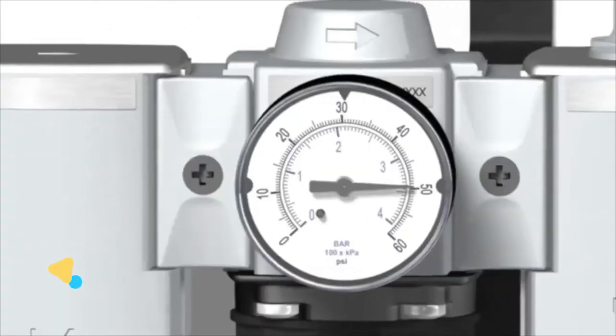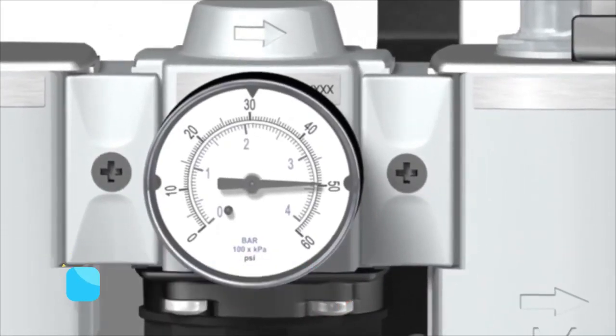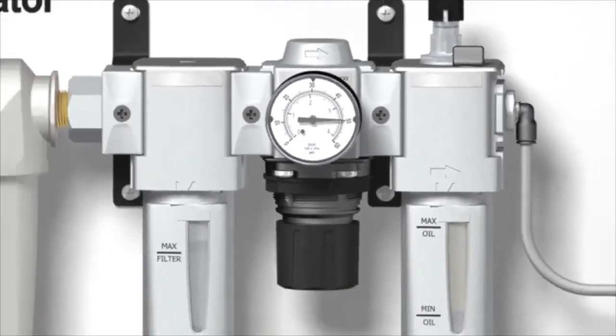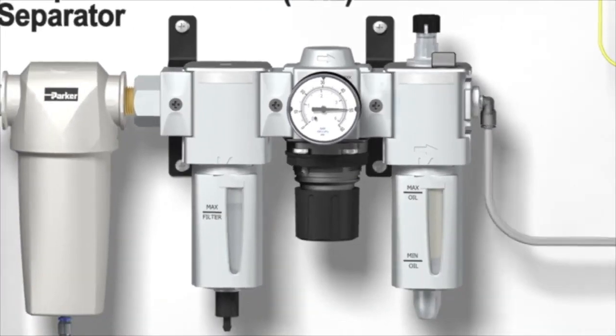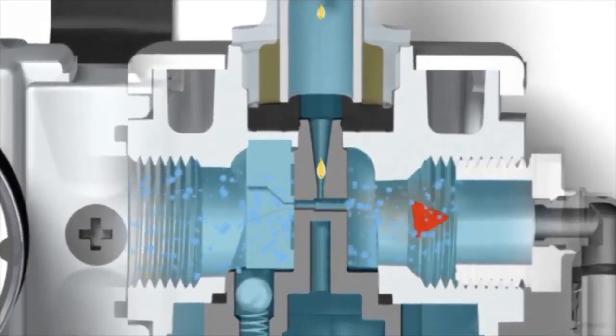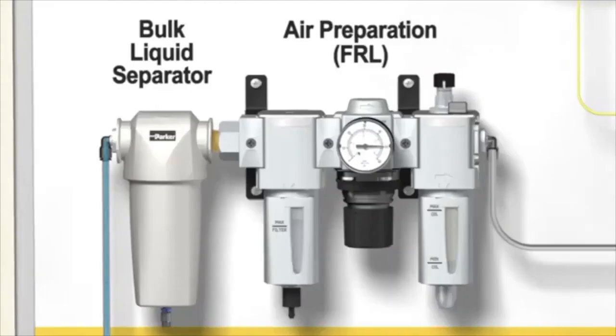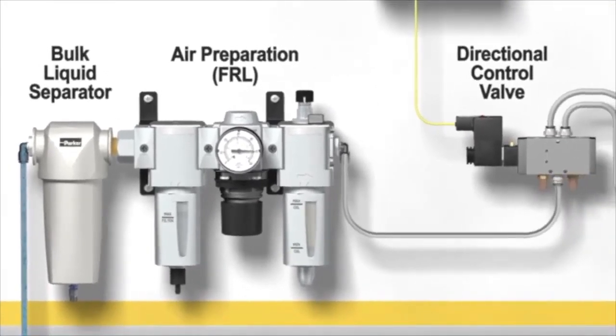Number 6. Air pressure regulators reduce supply pressure to the level required for efficient operation of pneumatic equipment. They reduce a supply or inlet pressure to a lower outlet pressure and work to maintain this outlet pressure despite fluctuations in the inlet pressure. The reduction of inlet pressure to a lower outlet pressure is the key characteristic of a pressure regulator.